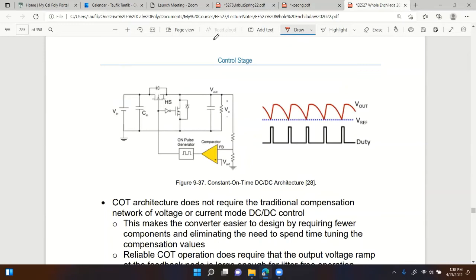So those are just explaining it through words. But if you look at this circuit diagram, and this is the waveform that we conceptually implement in constant on-time. Let's see if I can explain it, and hopefully it's clear. What's happening here is that it does not have that clock. That's number one. That's one of the reasons why it was slow, transient wise. So you can see there's no clock there. Interesting, and you can see how much simpler it is compared to current mode.